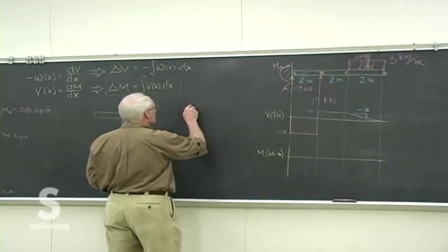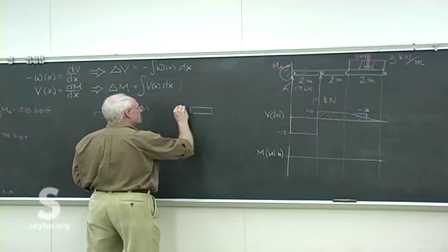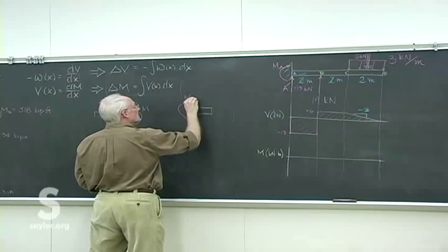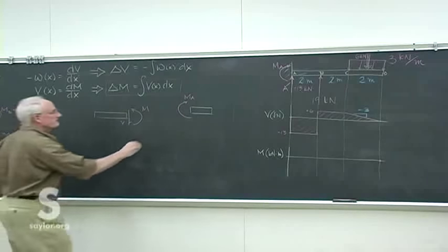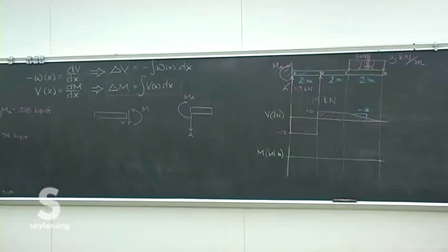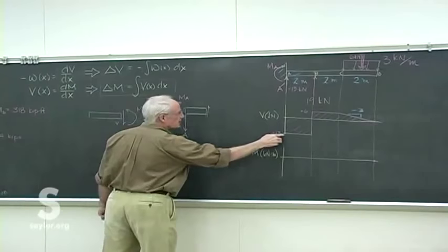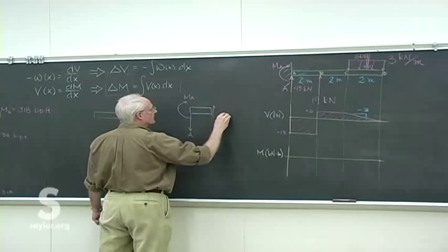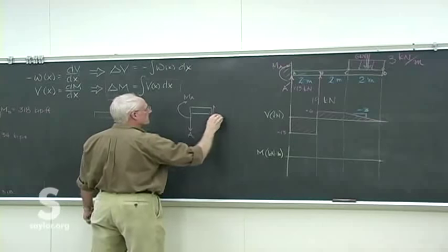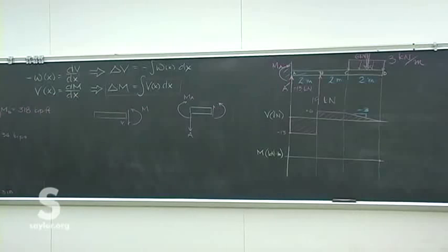So if we draw that in, with MA in the proper direction, nobody's yet given me the magnitude. A is actually in that direction. Without that wall, that end of the beam would go up. And then if A is down, we know we want shear going up, so that's why it's negative there. That's our negative direction. But the moment must also be in that direction.